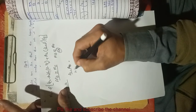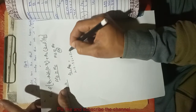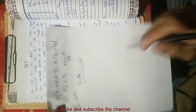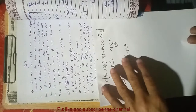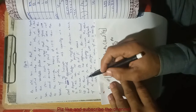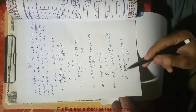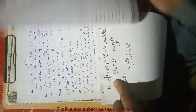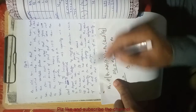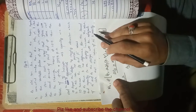The difference, 10.12 minus 9.60, is 0.52 square inches. This is a little bit of increase. As there is less difference between the demand and capacity, as you see here 1040 and 1030 are close, we slightly increase the value of As prime and As. The design will be adequate.